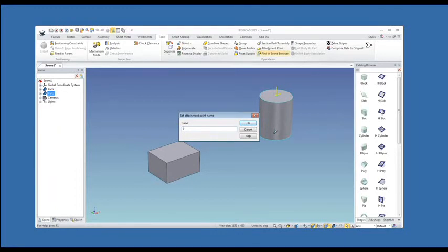Then you have to have a postfix to tell it what kind of attachment point it is. The most basic one is neutral, so you just do a name underscore neutral. I'm just going to do 1_n for neutral. You can also do male and female. I can do an _f or an _m, and an m will mate with an f and vice versa, so you can determine which end is up if you have mating connectors, things like that.